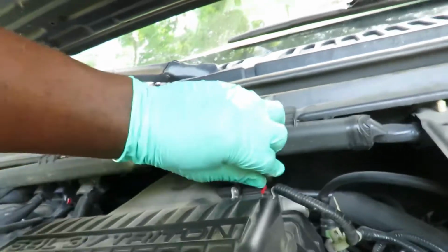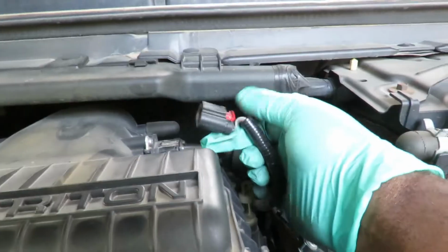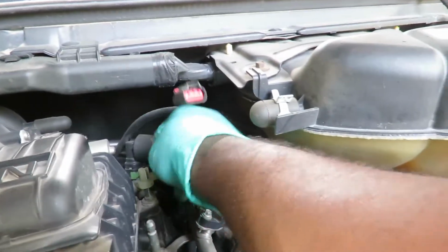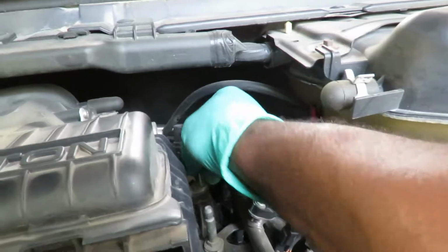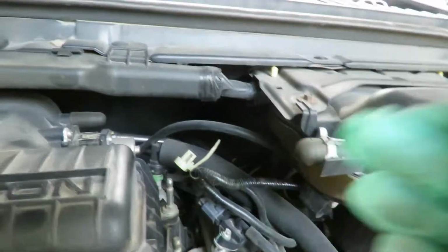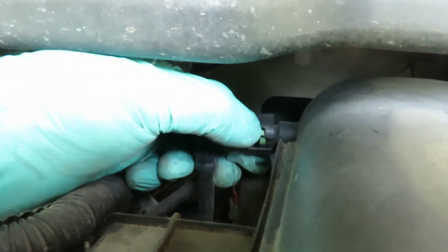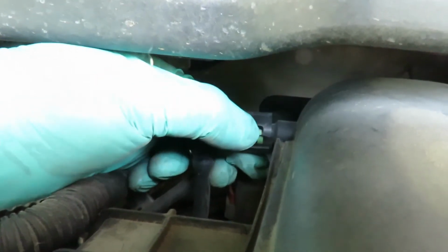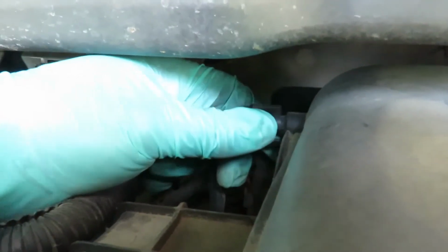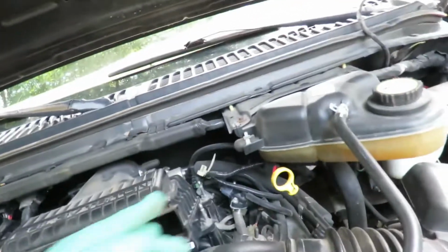And we're going to have to unplug it. Going to pull that little tab back like that. Squeeze it, unplug it. Then we're going to have to get this off of here. There we go. Pop off, put to the side. Right now, also with this cleaner, we got a little vacuum line right here. You see a little green tab? You're just going to push that green tab down. See that? Push it down, it'll release it and pull it off, just like that.